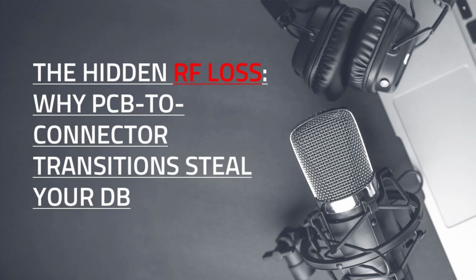And then you design your own board. You add a connector and a cable so you can mount the antenna where it actually fits in the enclosure. And now suddenly you're down a couple decibels and the range is a little worse than you expected. There's no smoke. There's no dramatic failure. There's no big explosion. It's just a nagging gap between what the datasheet promised and what your prototype actually delivers.